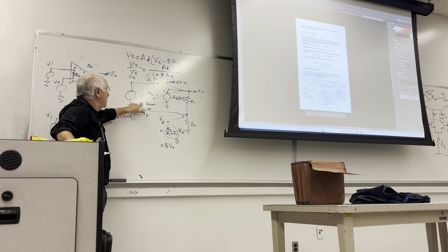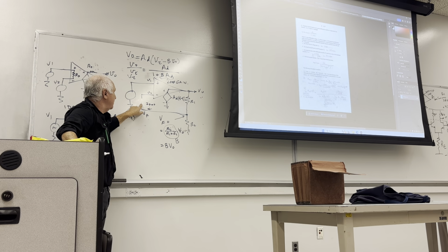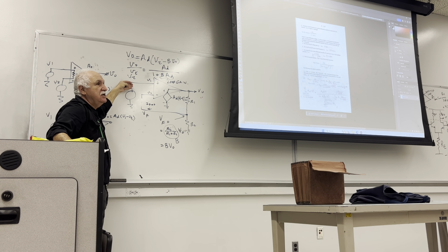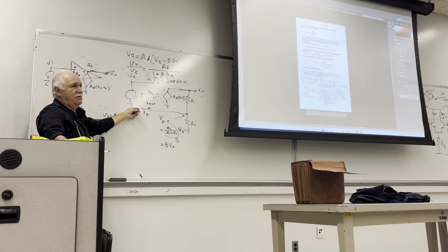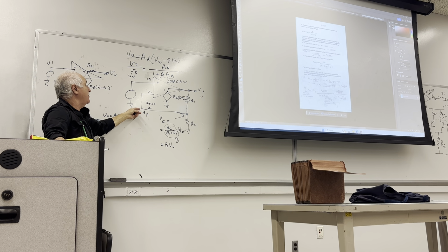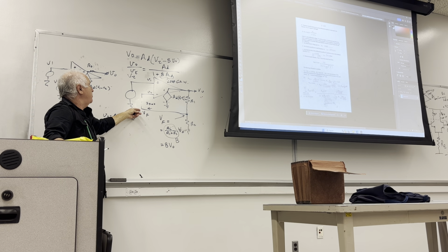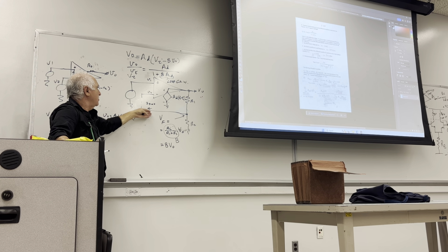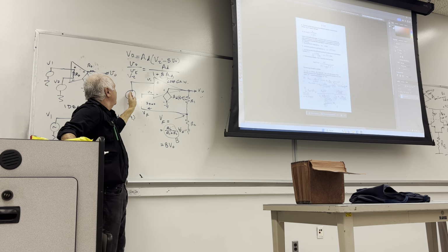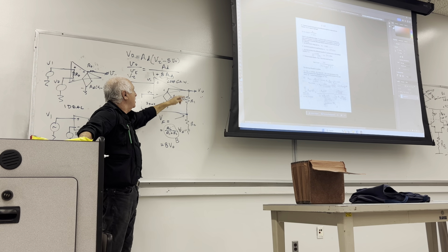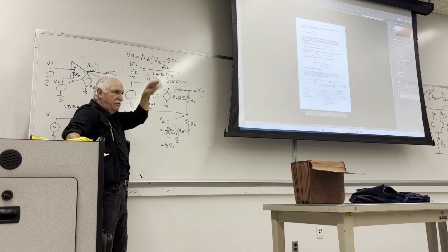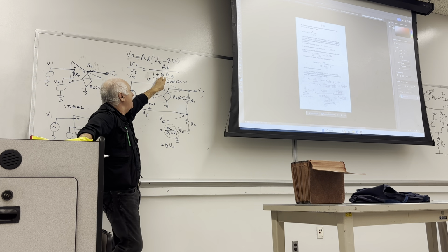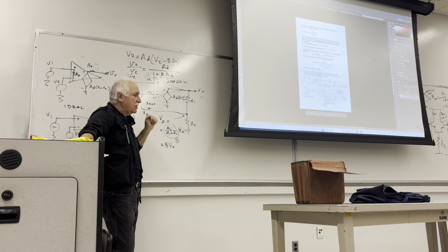output from broken feedback. So if you break this feedback, nothing. You inject a signal in here, what is going to come out back towards yourself? So pretending that what is coming out of here, if I put 0 here, and I inject the signal there, receive it here, of course. It will be A times, and then multiplied by the division in here, which is kind of a reduction, attenuation. So it will be A times B, known as the loop gain.